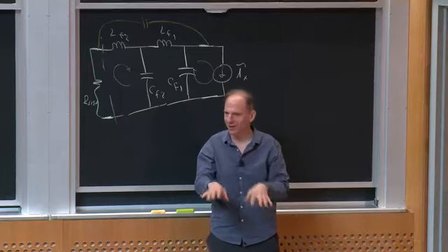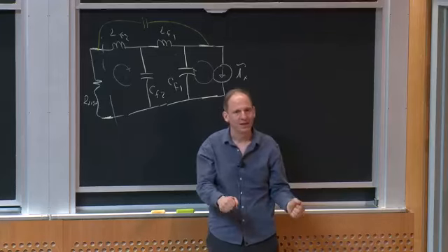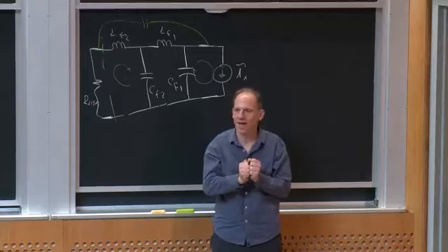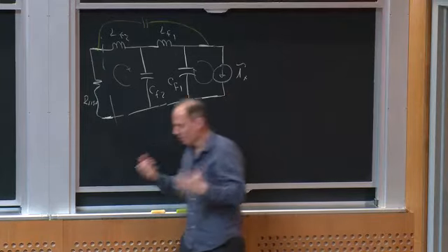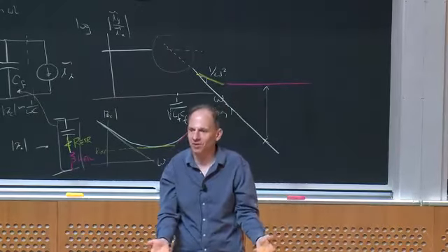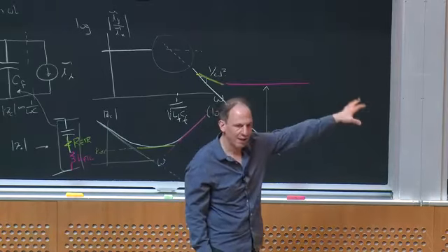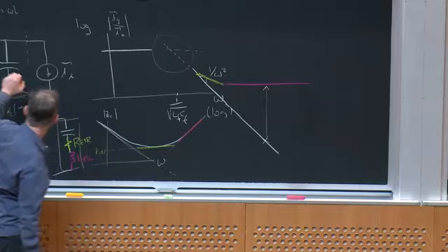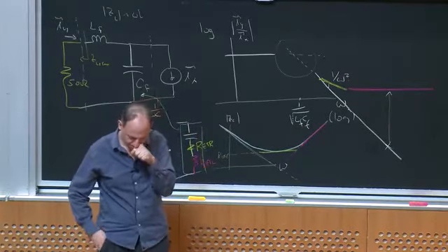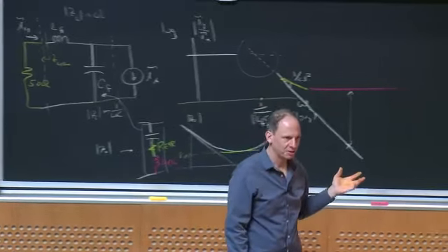So you've just got to be very clever about how you lay things out and keep things from coupling magnetically and keep things from coupling capacitively. And that's often an iterative process to get it to the point where you've realized what's going to happen with all the parasitics. So that's a way to, first of all, warn you what's to come if you go do this, and to not get frustrated, just look for where non-idealities, either layout parasitics or component parasitics, are going to come bite you, and then fix those.